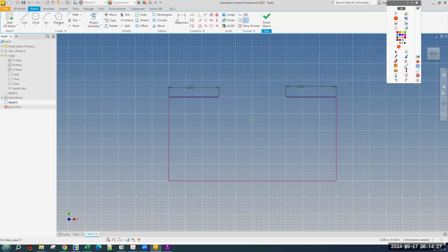Okay, so dimension tool, the distance from this point to the top, which don't choose the endpoint there, because then you might get the diagonal distance. It's the distance between here and this top edge. So you can click on one of those lines and it will let you dimension how far to the bottom or how far from the top, which if you do a little math, it's 5 tall. And we wanted 2 from the top, which is the same thing as 3 from the bottom. Either of those will work. The second way is probably a little easier to click.